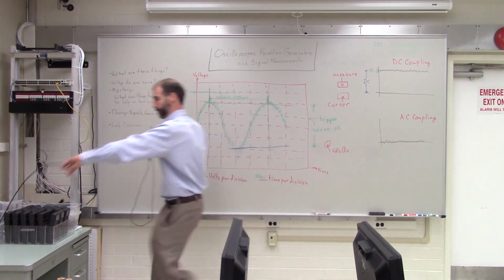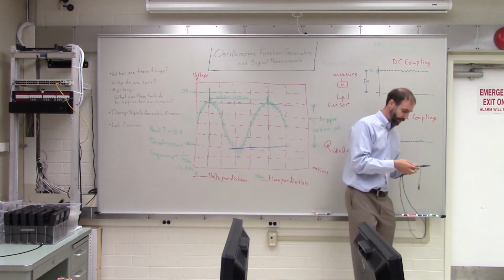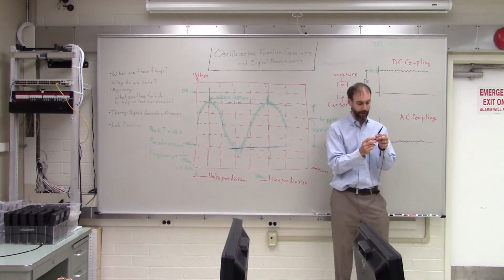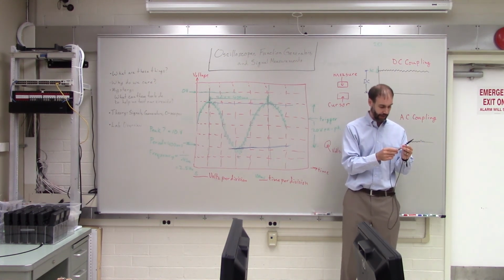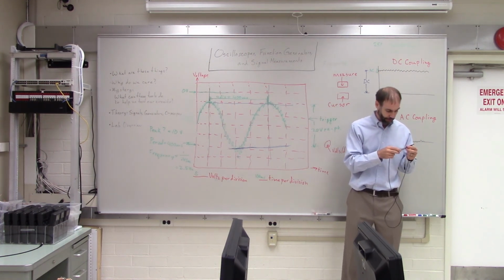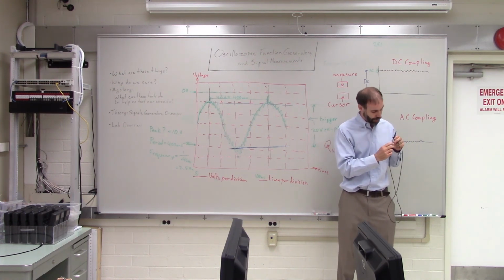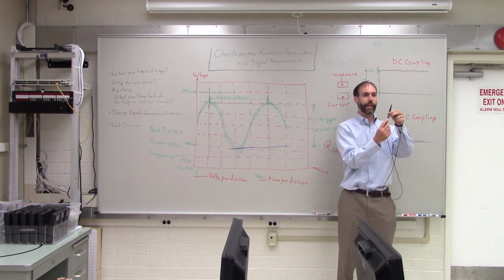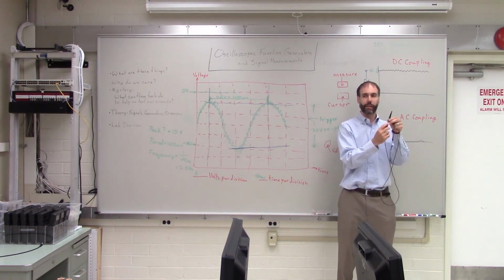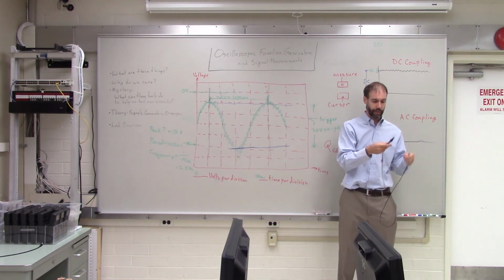The oscilloscope probes, while we're talking about them, have this little switch, and this is going to screw you up. This is going to screw you up a lot. I can't count the number of times that this has really been a problem for people, including myself. This little switch goes between 1x and 10x. You always want it to be in the 10x setting, which is down, away from the point.